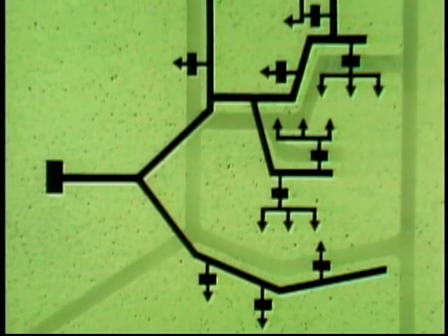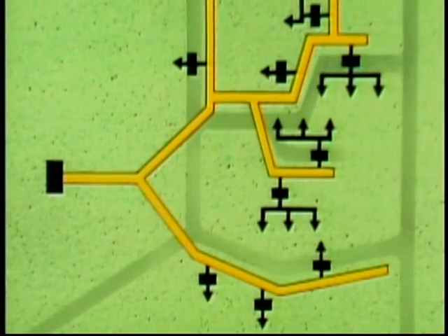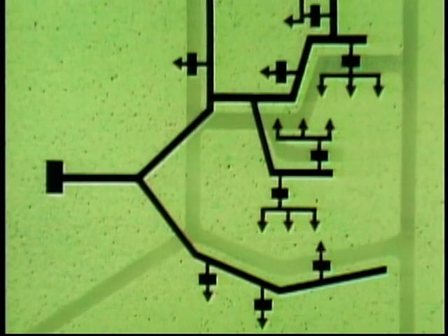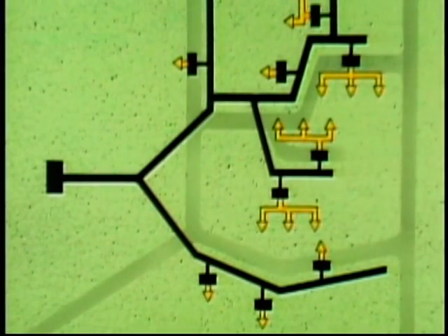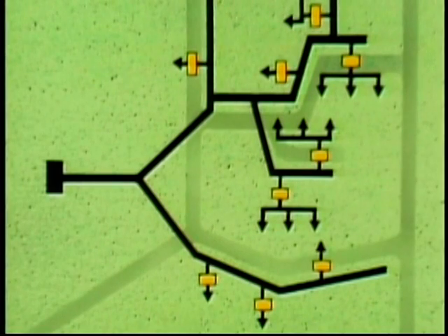A distribution system is typically made up of two connected systems. One of the systems, called the primary distribution system, delivers power at a distribution voltage from a distribution substation to various distribution transformers. The other system, called the secondary distribution system, delivers power at a user voltage from the distribution transformers to the customers. The distribution transformer is the connecting link between the lines of the primary and secondary systems. It takes voltage from the primary lines and steps it down to a secondary system voltage.